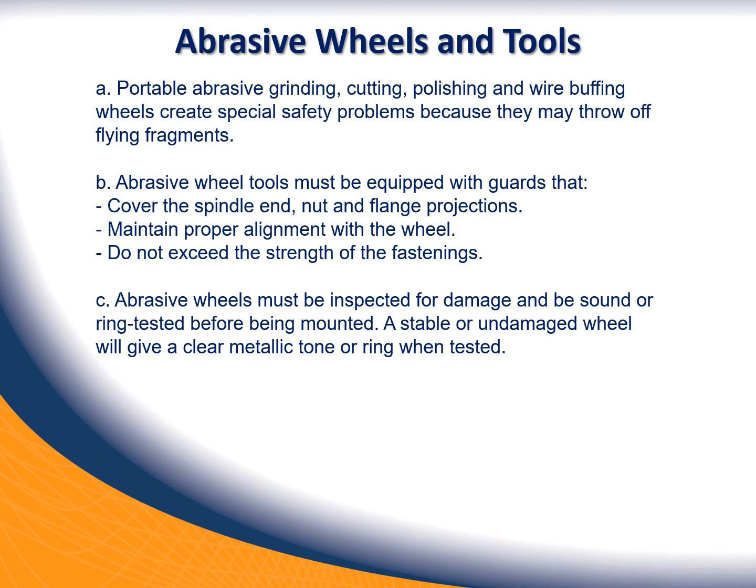Abrasive tools, that's like a grinding wheel. The biggest thing there is to make sure your grinding wheel is in decent shape. If it's pitted or in bad shape, there can be a hazard. It can actually fly apart when you're using it. Make sure the alignment's proper. You have to have the right distance on the work guards so that your finger doesn't get stuck in it. And make sure that they're in decent shape before you use them.